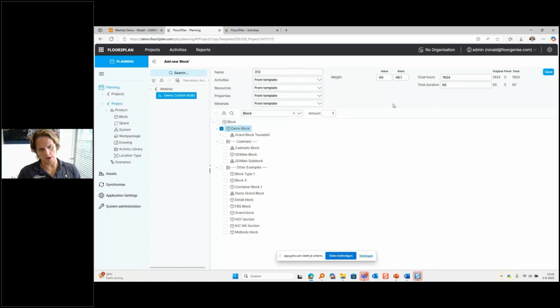And we know from our rough construction plan setup that it will weigh around 50 tons. Then we have an internal ratio of 50 man-hours per ton. So therefore, we need to distribute, or consume ultimately, 2,500 hours of effort in construction, or in production, in these 84 days of production.